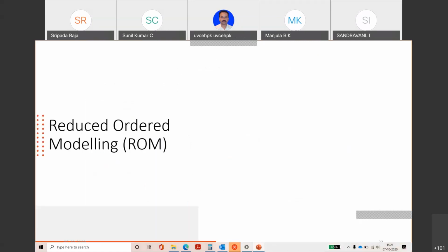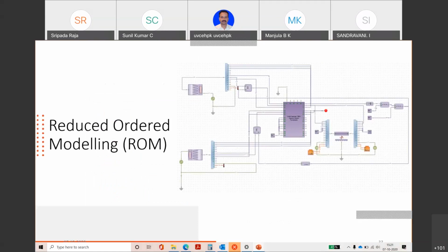So once the HDL file is created, I can connect the signals coming from these MEMS devices to a signal conditioning system. I want to read or process these signals. These things are not possible in FEM simulation. So that's when reduced order modeling helps us.